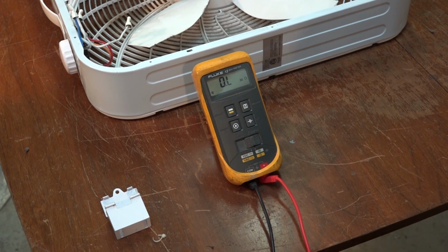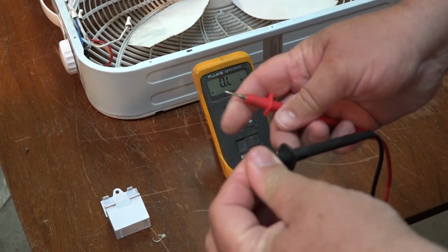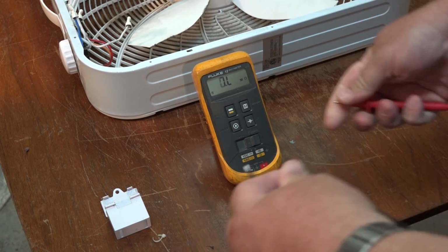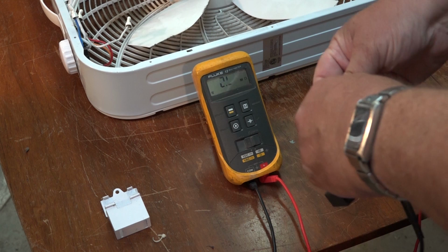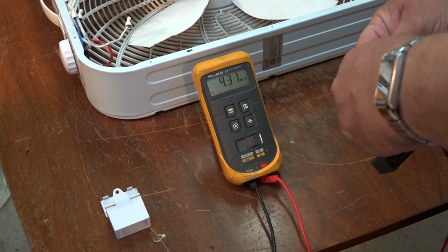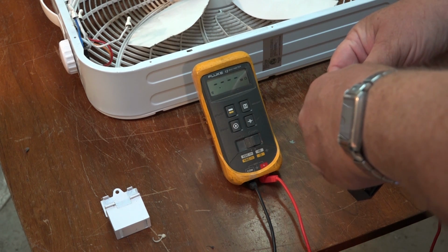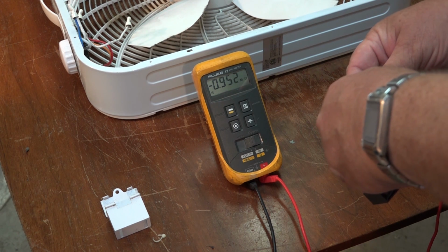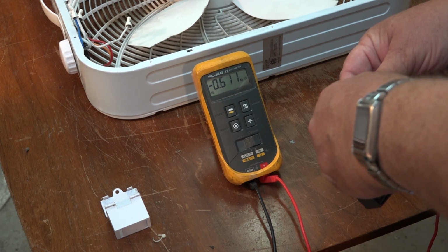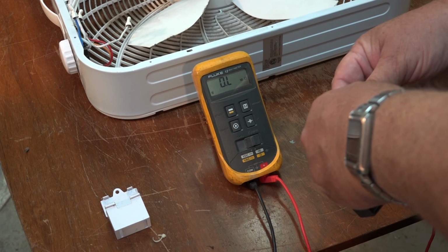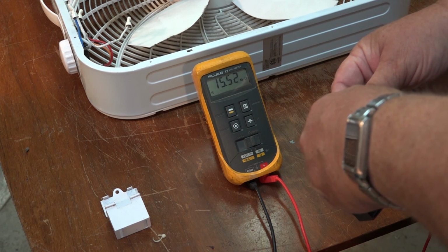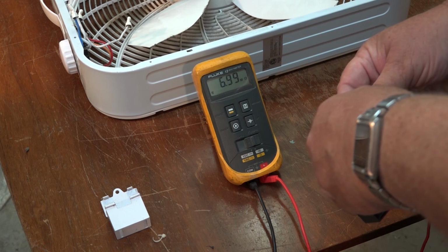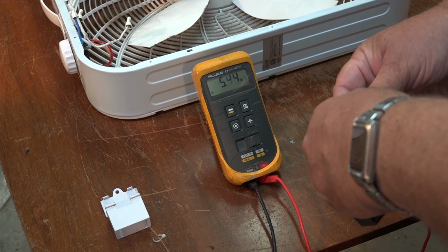Normally when you measure a good capacitor, we connect our probes up, and what will happen is that the ohms should drop very low initially, and then they should go high. But this one here, as you can see, my ohms is... so it hasn't gone open, but it's actually built up resistance.